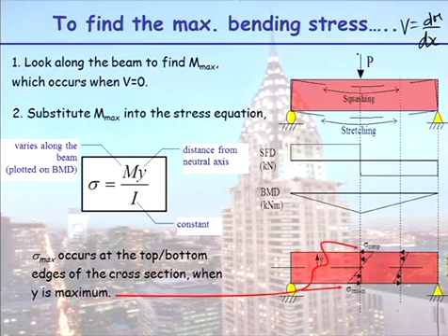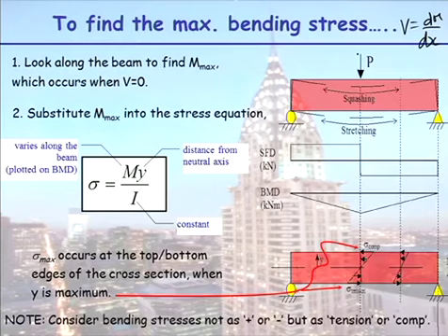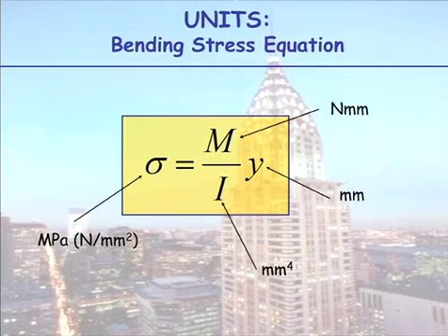So let's now do a problem. But I think before we do the problem, I need to point out what's plus and what's minus. Once again, tension we refer to as positive, compression negative. So when we use this formula, we don't think of y as having plus or minus values, we just calculate the stress. We look at how it bends and we go, oh, there's squashing in the top, that's compression. So don't bother defining y to be plus or minus. This is what I thought I had to point out.